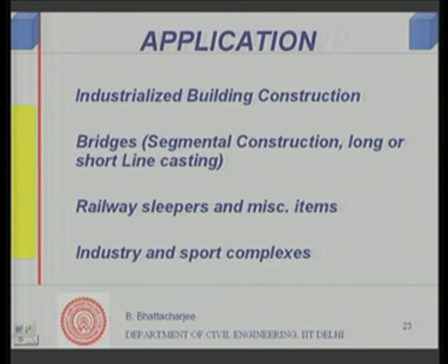In short line casting, you cast one element and then cast the next element by the side of it, what is known as match casting, and then remove that one. But in long line, say for one complete span, you will have molds placed for the whole span, and then each element is cast one after another together. So, that is long line casting. So, bridges, this has been used in India.